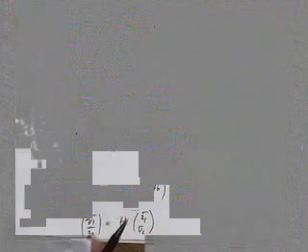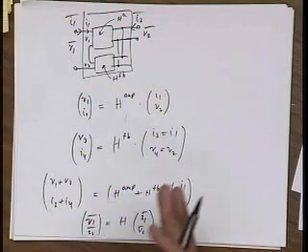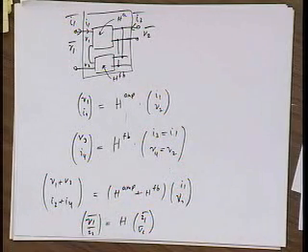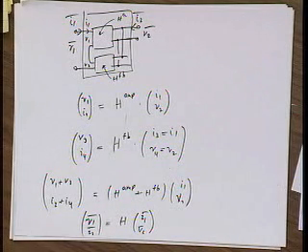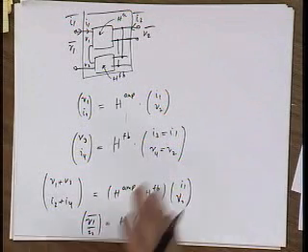The reason I went through this exercise is that it's a little bit different from the Y parameters. It gives you a little bit of flavor. And I leave it to you to look at the Z parameters, right? That's for series feedback on both sides. And the G parameters, which are the inverse hybrid parameters. So exactly the opposite type, which would be for a current amplifier. Right? Current input, current output.